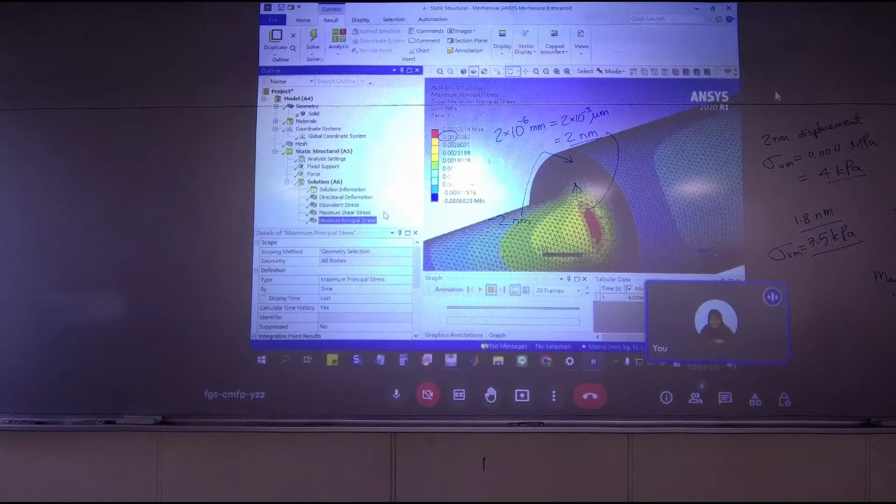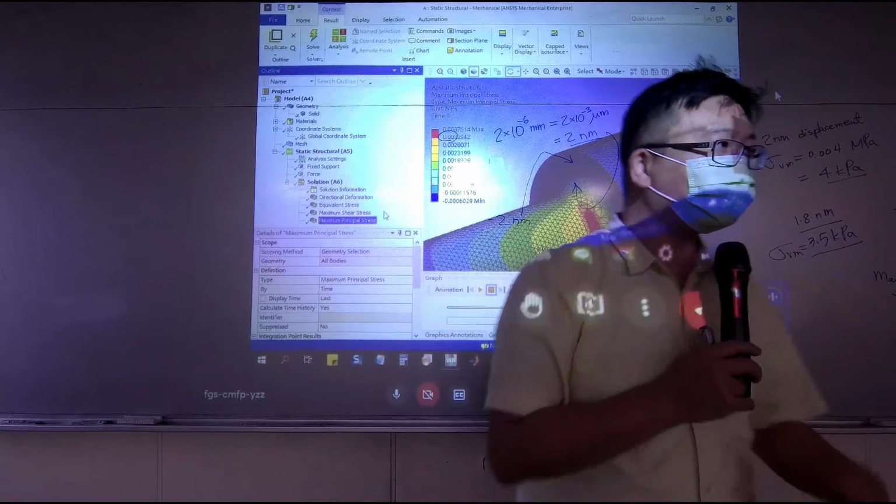And when we introduced this model, we said maximum shear is more conservative. On the other hand, the maximum distortion energy is more aggressive. Okay? So that's why if we use von Mises stress, the estimation of your safety is higher. You are not conservative. Okay, so please try to combine what you learn with what you work on in the future. And you need to make your own decision.